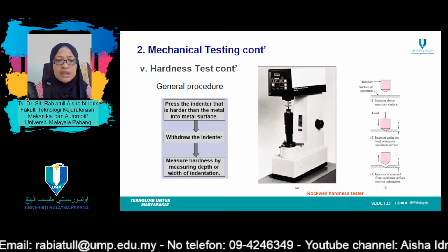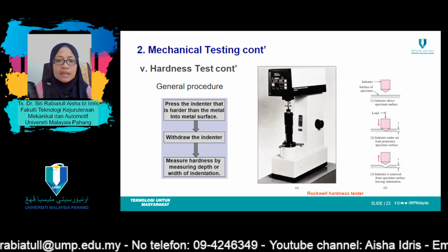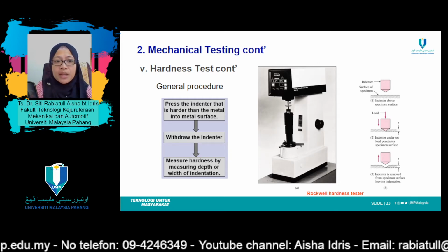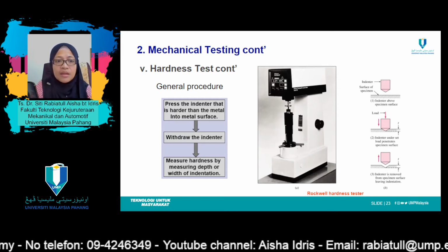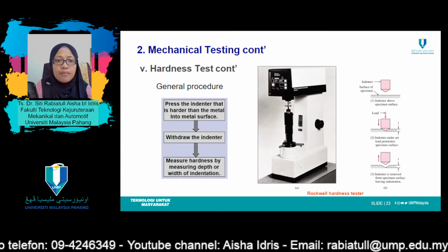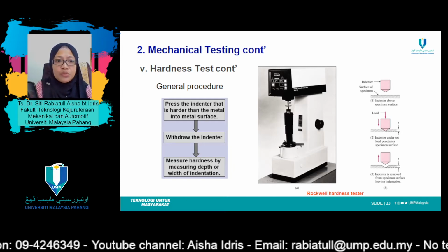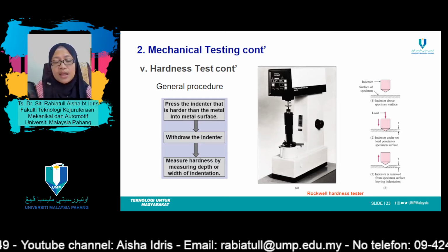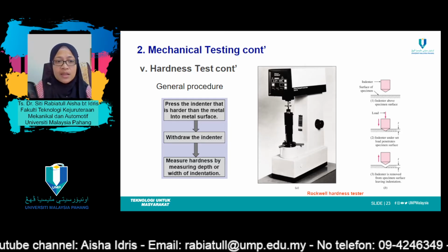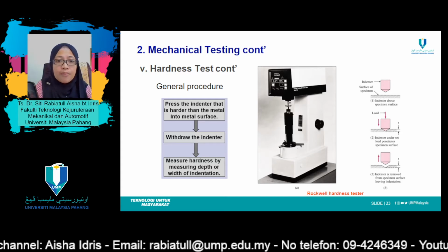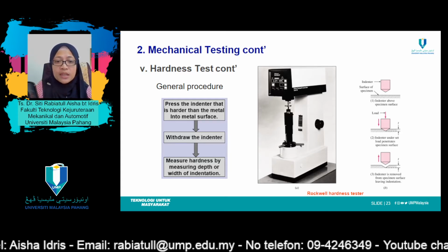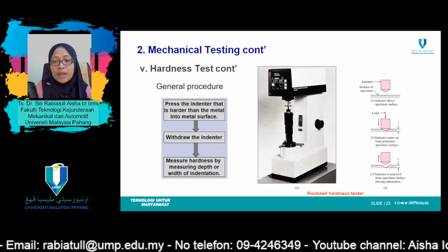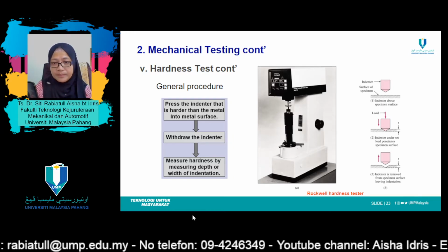Hardness is determined by measuring the depth of indenter penetration or the size of the impression left by the indenter. Tests that measure the depth of penetration include Rockwell, instrumented indentation testing, and ball indentation hardness, whereas tests that measure the size of the impression include Vickers, Knoop, and Brinell testing.